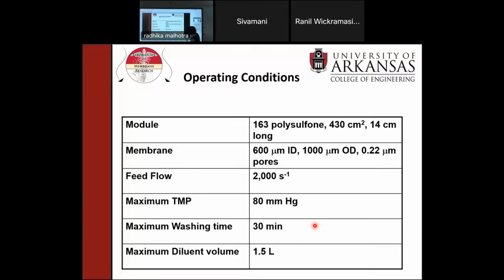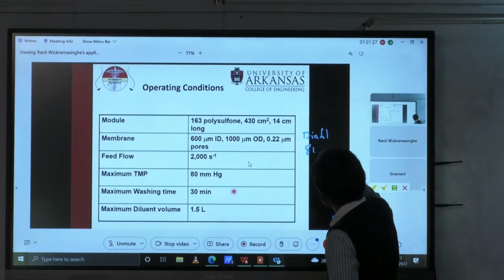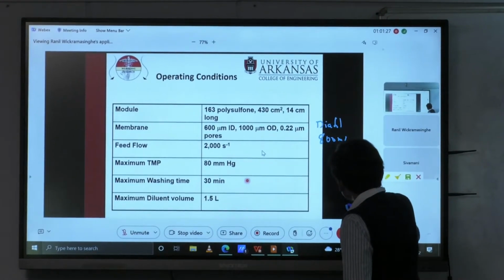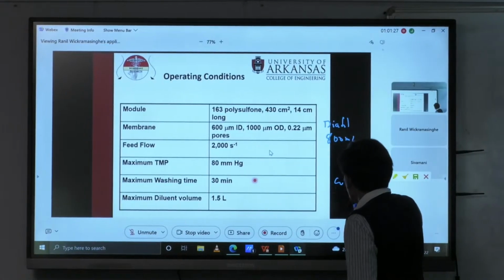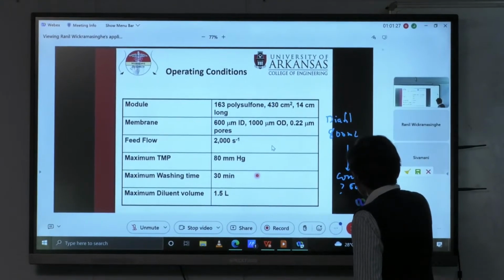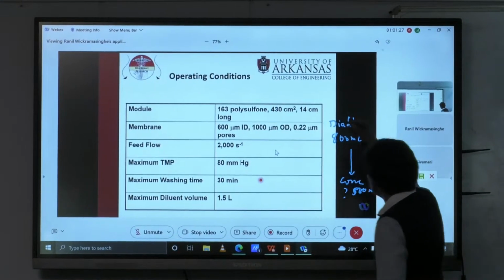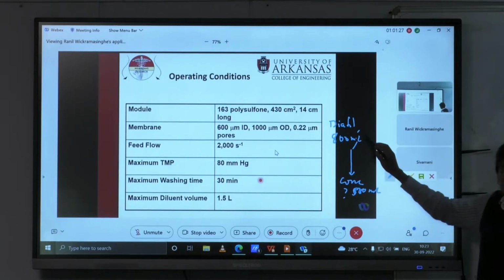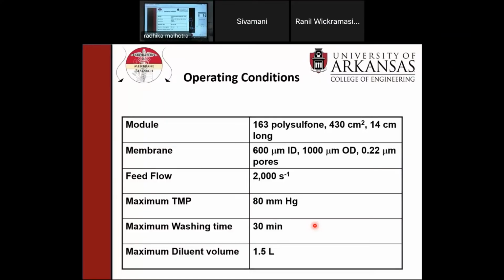So do you start off here and do diafiltration first, okay, at 800 ml blood volume, and then concentrate to whatever it is, and actually it's about 540 ml, something like this, okay? So do you do the diafiltration first and then concentrate? So what's the advantage of this? Well, if you remember our flux equations, the lower the cell concentration, the higher the flux. Processing time will be shorter, okay? What's the disadvantage? If we are using, say, 3 dia volumes, you need 3 by 800 ml of saline diluent.